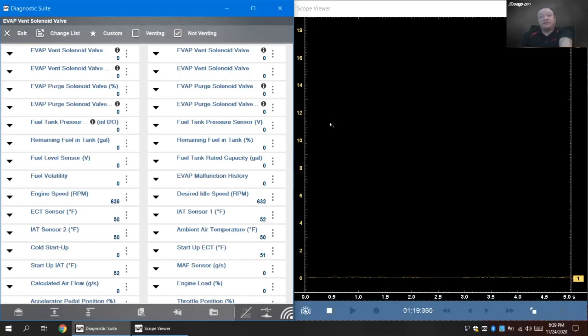Yeah, so let's say I see 12 volts up here, right? So if I had 12 volts in and 0 volts out in any state, then that indicates an open inside the solenoid. And that means the solenoid is bad, right? I'm able to test that on the screen, and I'd be able to see what's going on. Now, if I did see 0 volts and then 12 volts as I'm switching it on and off, then I know the solenoid is working, and I know the ground supply is working too. So I'd probably have to look for an intermittent problem of some sort.